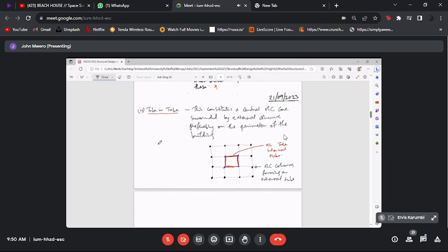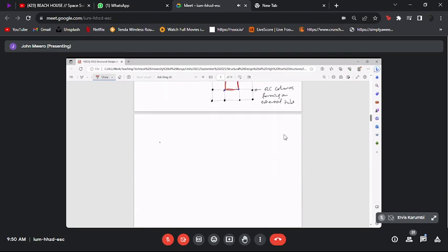Okay, the last one, and I'll show you a real life example of this shortly. Let me just highlight the last one, so that when I show you this example, you see all of it. So now, if you have a tube in tube building, and maybe the height has become too much and it's swaying too much, you could actually have something they refer to as an outrigger system.